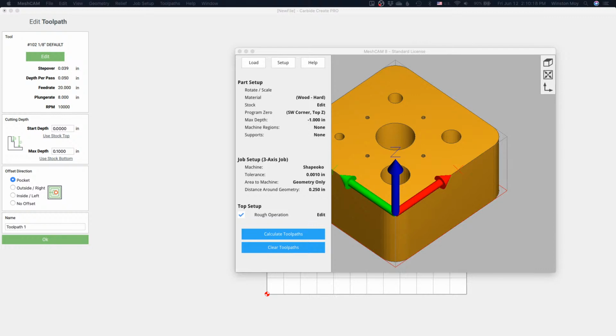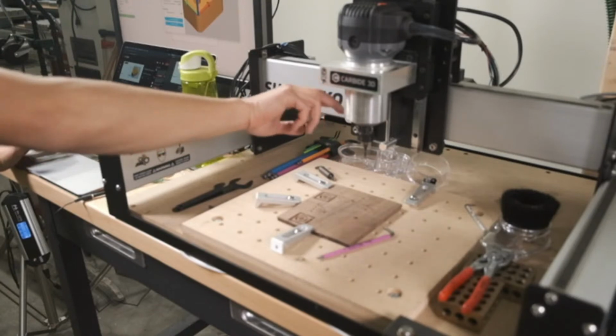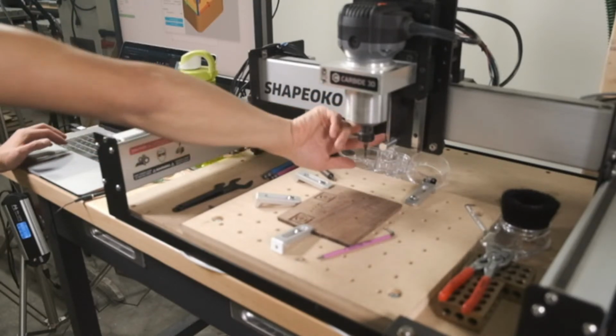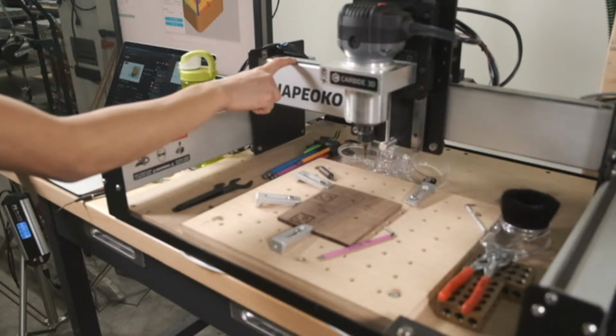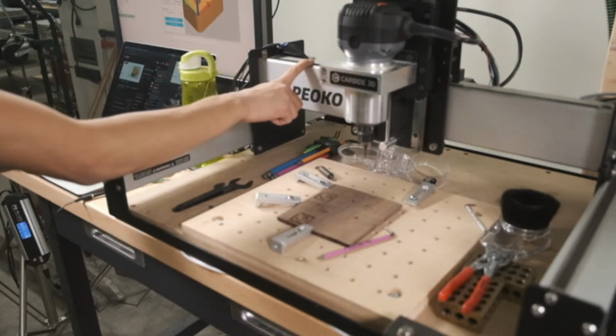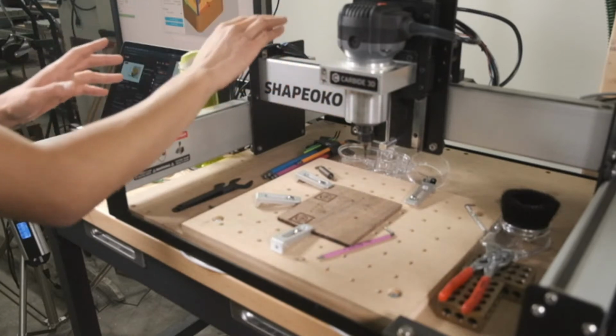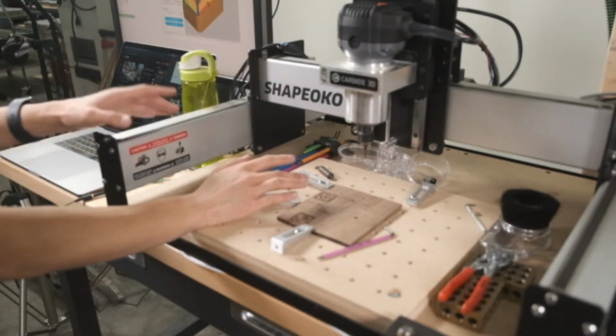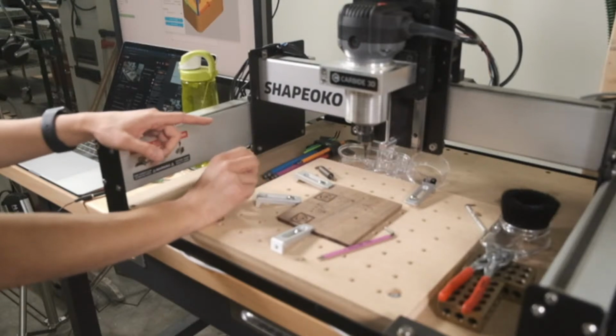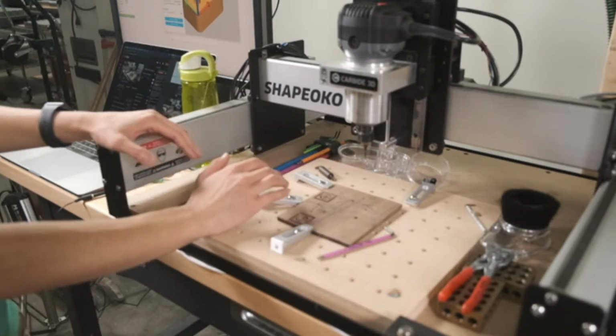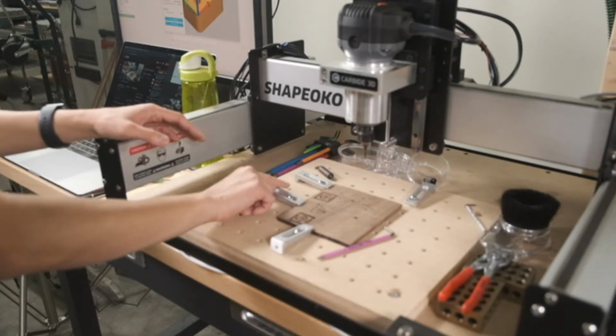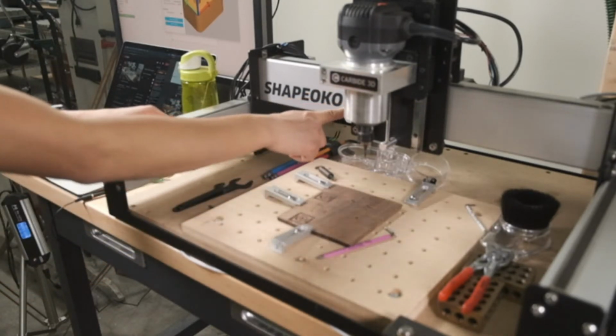Building a new CNC for the first time, any tips for improving rigidity, belt, or lead screw? If you want more rigidity, definitely go for the Z Plus or the HDZ with the lead screw driven Z. It's a bear if you want to try and DIY a lead screw for the X and Y, so I wouldn't recommend it. I'd say just try the machine first. You can always mod it later, but we think the stock experience is good enough for like 95, 99% of people. But get a good Z-axis and go from there.